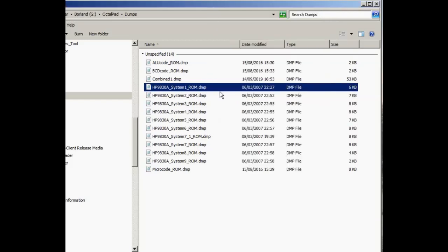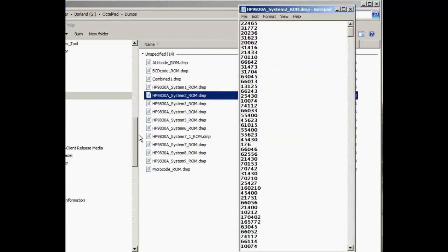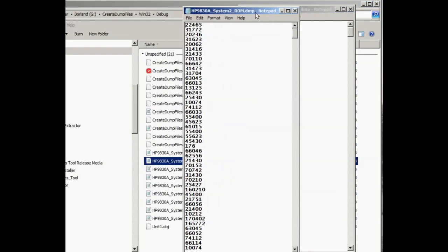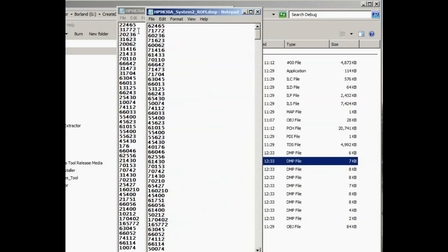Now if you recall from the video in which I looked at the data on the analyzer, it was a second set of ROMs that initially were causing the problem. So if we open the second ROM set, so we now have both ROMs, you'll see straight away there is an issue in that they're not the same, and it appears to be a single bit error, so it's unlikely it's just a simple firmware change. It could be, but it's unlikely, and it does seem that one bit on the ROM in this location on the board is stuck, it's faulty.